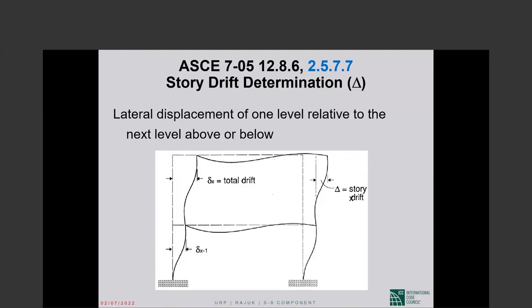We are trying to keep machinery that is mounted on our floors functioning. So the drift check has to do with controlling property damage and to make it more likely that the structure will go on functioning during and following an earthquake. This is beyond life safety.